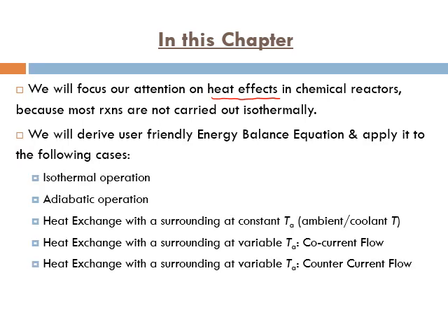We will derive user-friendly energy balance equations and apply them to the following cases: isothermal operation, adiabatic operation, heat exchange with a surrounding at constant ambient temperature, heat exchange with a surrounding at variable ambient temperature with a co-current flow, and the last one is with a counter current flow.